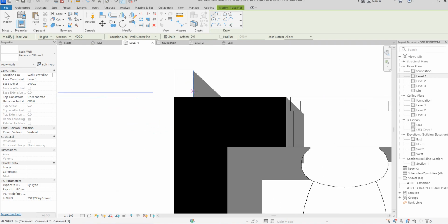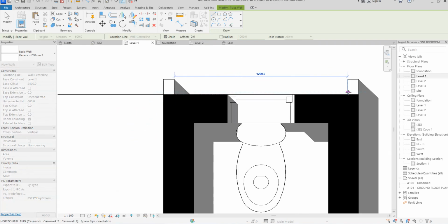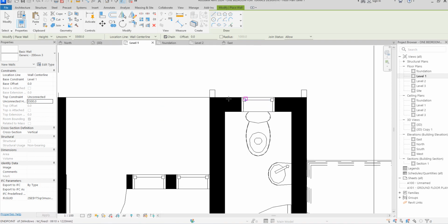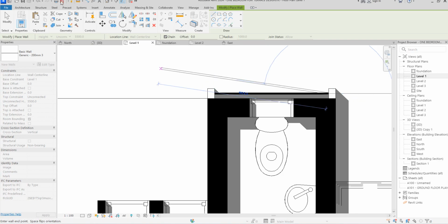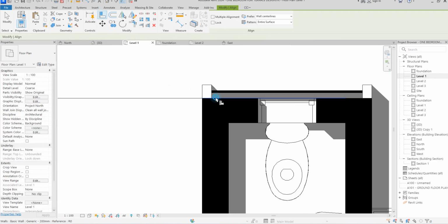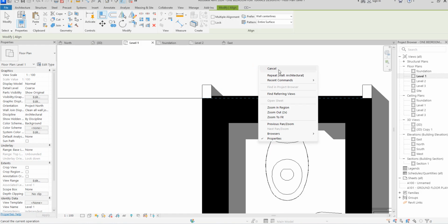So what I do now is that I will select here. So now the problem is that I'm having issue with the wall because I've changed the perimeter here. So I'm going to return this back to 0. While this one I will give it like double, let's say 5005, because I want it to start from ground and touch the upper part. So I'm going to do this like this and then fix it up. So now I will select and put it here. So I've done with this one.